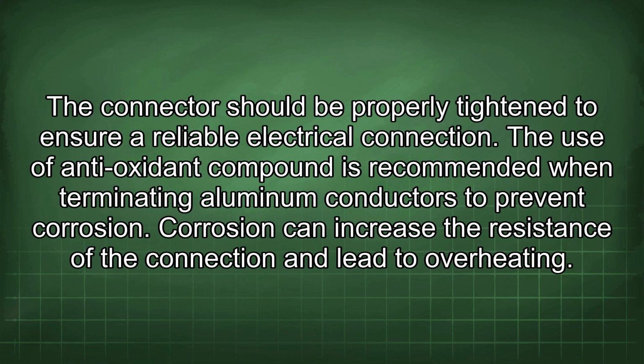The use of antioxidant compound is recommended when terminating aluminum conductors to prevent corrosion. Corrosion can increase the resistance of the connection and lead to overheating.